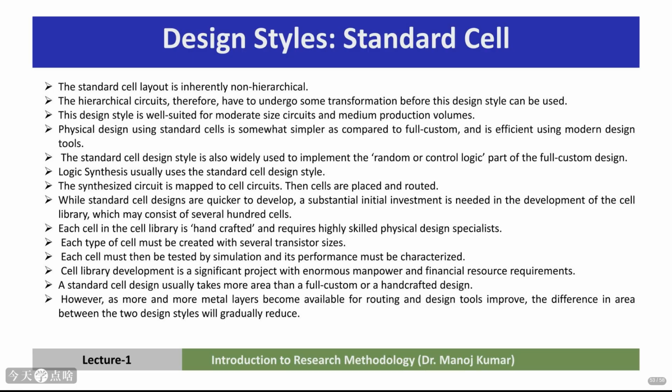Logic synthesis tools often target standard cell libraries. While faster to develop than full custom, creating the cell library itself is a massive undertaking, requiring skilled designers and significant resources. Each cell needs to be simulated and characterized. Standard cell designs typically take more area than fully optimized full custom designs, but the gap is narrowing with better routing tools and more metal layers.